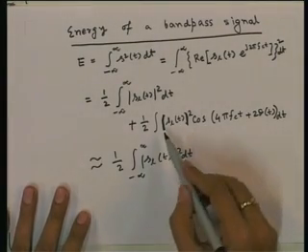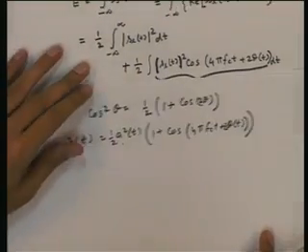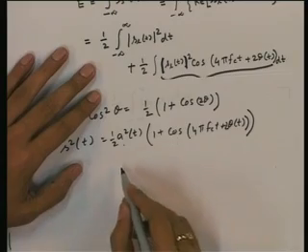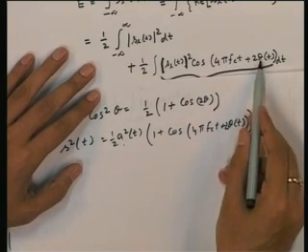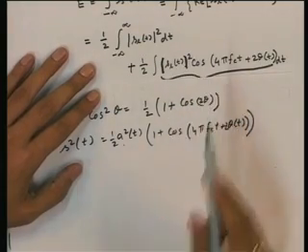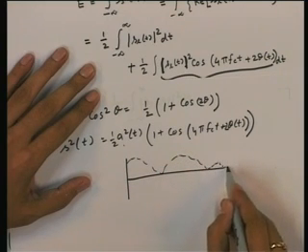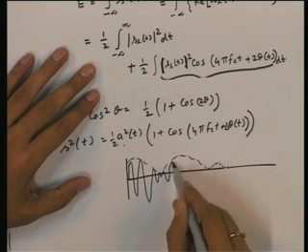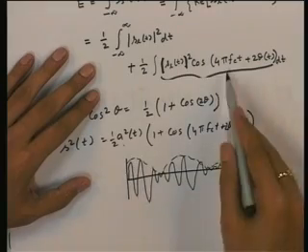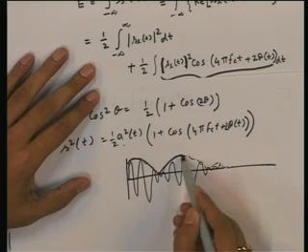Why? What are we integrating in the second integration? If you try to draw the waveform of this inside function, it will also be a bandpass signal, because this is a carrier signal with frequency 2 fc and phase 2 theta t, and the envelope is the magnitude of s_l(t) squared. So, it will look like this, with the magnitude of s_l(t) squared as the envelope, and then this is the signal. Here 2 times fc is usually a very high frequency, and the envelope is a baseband real signal. We are integrating this signal.